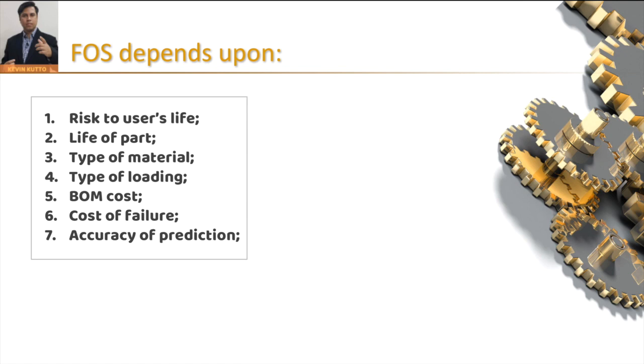But most of the time we are working in an industry which has been there for ages. If you are designing a seating system, they have been designing seating systems since long. You are designing instrument panels, suspension systems, engines, they are there since long. So we understand these systems in great detail, and that's why the probability of your assumptions going wrong is minimum, and that's why you have to be reasonable in selecting your factor of safety. So if the accuracy of prediction is high, lower factor of safety. If accuracy of prediction is low, higher factor of safety. It's very easy to understand.